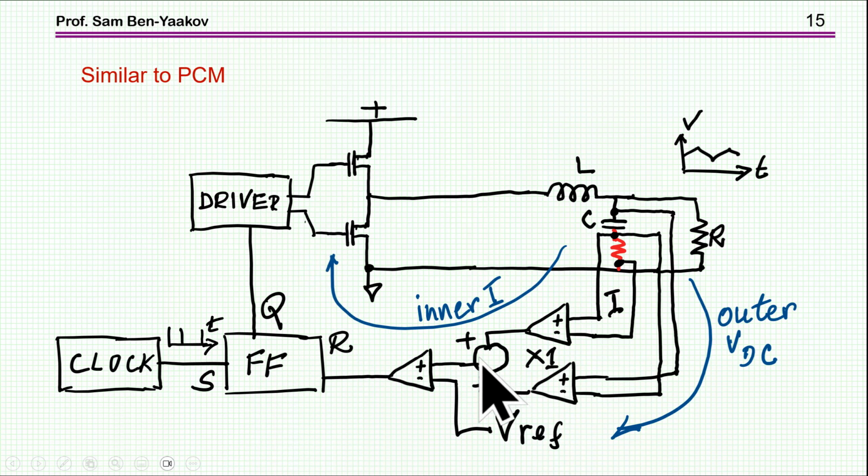So it's not a surprise now that, like in the peak current mode, you are going to have the problem of subharmonic oscillation. And again, this is explained in the video that I've referenced and will be printed in the description section of this video that you are now watching. So to see that indeed slope compensation is helping, I'm generating here a slope. I could have taken it from here, because here we have a square wave, and then with a resistor and capacitor I could have generated a slope, but I prefer to do it this way.